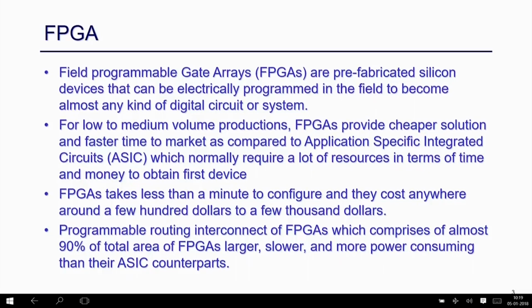The advantage of this FPGA is that it is very fast. Whenever you have RTL, you can easily map it into the FPGA using a synthesis tool provided by industry vendors like Xilinx, Altera, Synopsys or Cadence, and you just use it. On the other hand, in the ASIC flow the whole process is very time consuming, and it does not make sense when the number of chips you require is very small. If you just need one or two chips or designs, you do not go for ASIC, because it is a time consuming and also costly process.